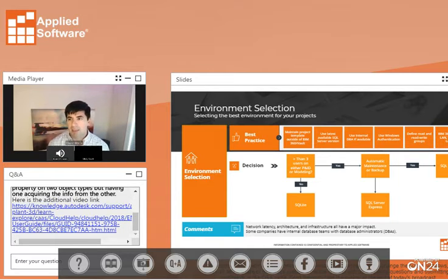That scenario is best done inside of Autodesk Vault, because Vault has what they call electronic change orders, and so you can kick off a process like that. In addition, it has another capability in Vault called life cycles. By using Plant 3D inside of Vault, you can assign life cycles to drawings. For example, we do this in our Plant 3D Boost project: if they're a work in progress, we can make changes to it, but once we want it pushed out to the cloud for our customers to use, it goes to released, and that release process pushes it to BIM 360 so that people outside of our network can get access to it. So that is the main use case for Vault.